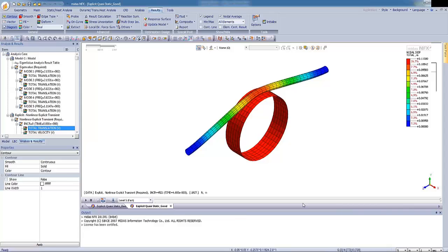So when we want to perform this kind of simulation, actually we have to perform a series of simulations in the order from the fastest load rate to the slowest. And of course we have to examine the results. So we have to investigate the deformed shapes, stresses, strains and energies to get a proper understanding of the effects in our model. So that's all for today.